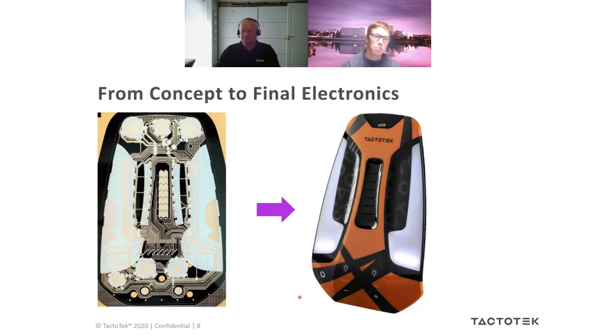In IMSC, we have thermoforming, which makes this electrical layout in 3D form, and the latest manufacturing phase is injection molding, where we put plastics on top of our components. By injection molding, we are encapsulating our electrical circuits and components within the plastic.